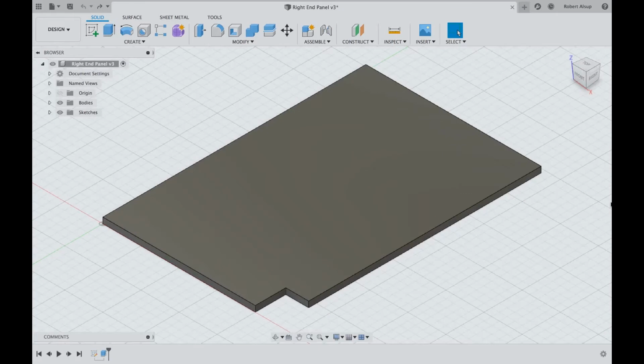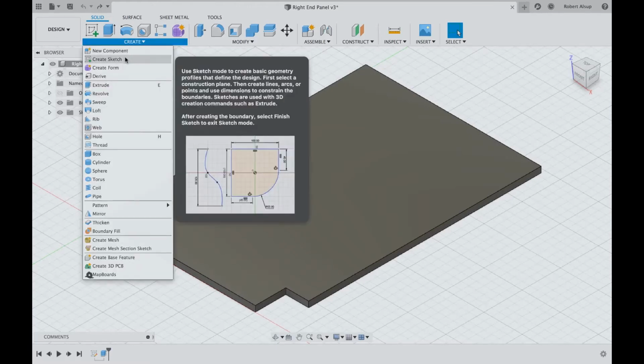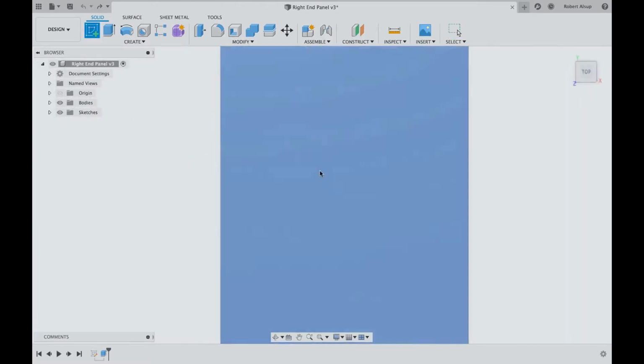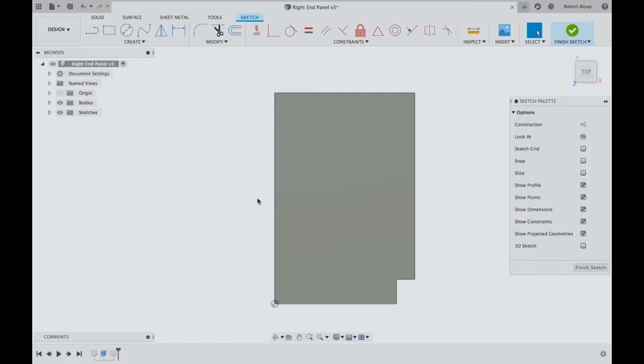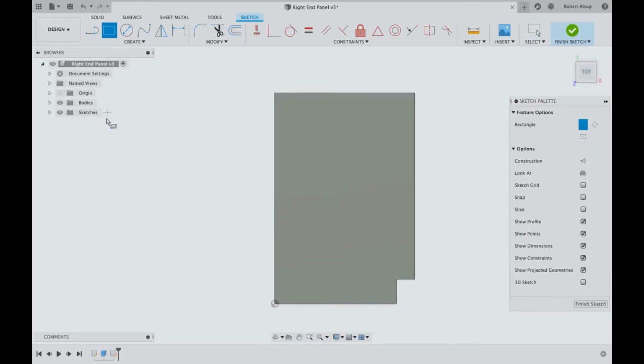Well, our cabinet part needs joinery. So think about, how would I do that in VCarve Pro? Well, I'd probably just draw some rectangles where the joints are and get them positioned, and then they would get toolpathed. Well, let's approach that the same way. So let's create a sketch that has the joints on it. So we start by Create Sketch, and we'll pick that surface and we'll bring it out a little bit. I have better luck drawing out here in the canvas than moving it over. So let's do this. Let's create a little rectangle.